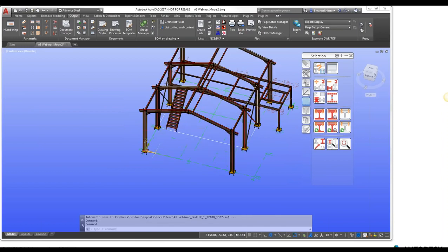The current UCS will be the one that decides how it will be shown. In this case, we have the X or Y orientation like that, the UCS orientation, so that overview detail will be oriented from the positive Z-axis looking to the X or Y plane.